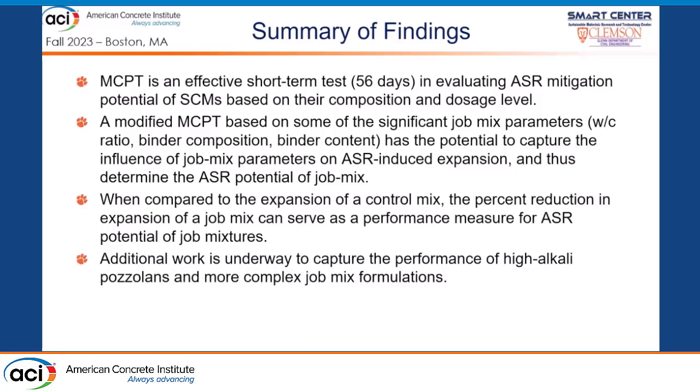My experience has been, yes, that is true. There are certainly certain SCMs that do that. One case in point is glass-based, type GS glasses, which I worked quite a bit with, and type GE glasses as well. But by and large, most SCMs don't fall in that category of alkali release type of SCMs.